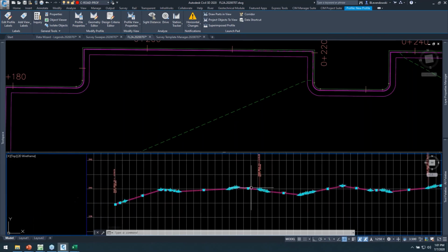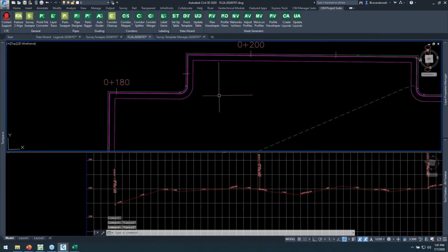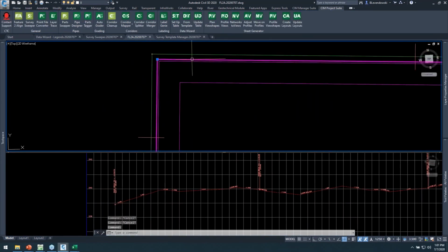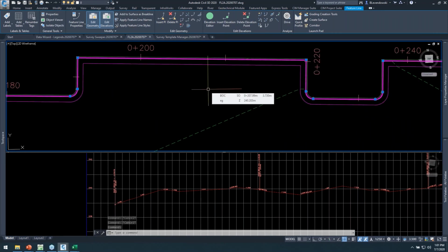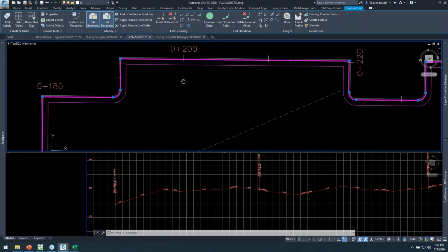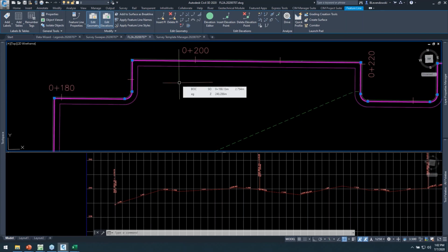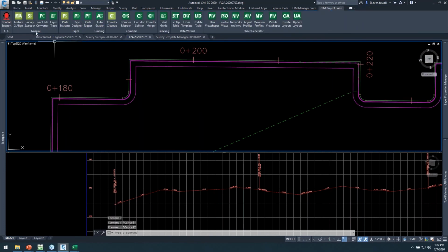And then here is the 3D geometry, the vertical profile, matching exactly what was in the feature line. So if your designers aren't using feature lines for grading, they certainly should be. Many workflows work great with feature lines. When they do that, you're able to take that and very easily export it for staking purposes like this. So that's a tool called Feature Line to Alignment.